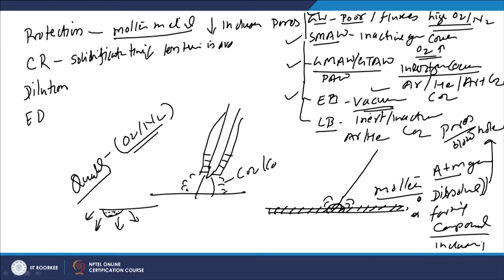is available for growth of micro constituents. Less time for growth of micro constituents means the temperature will be reducing from the molten melting point to the room temperature at a much faster rate, and therefore the time available for growth of micro constituents is reduced, and that in turn will be reducing the grain size.